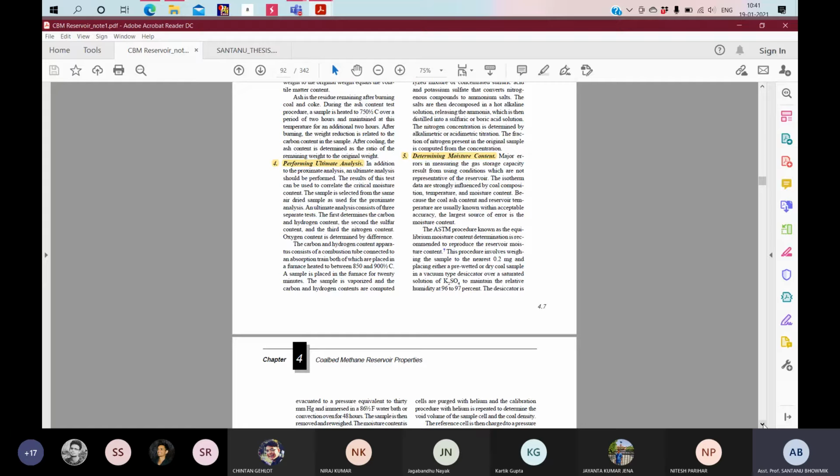At one point you will see that even if you add more water or there is further seepage, the moisture level of that seam does not increase. That means the seam is totally saturated with moisture at that pressure, temperature, and depth condition.